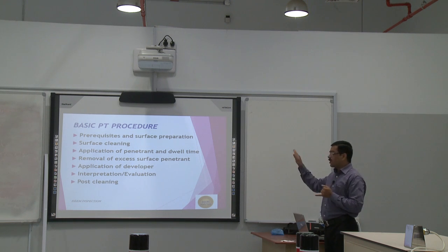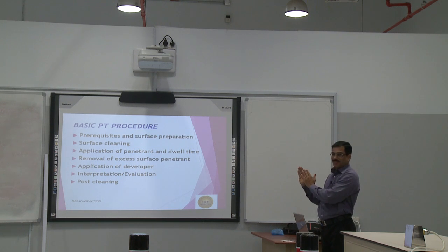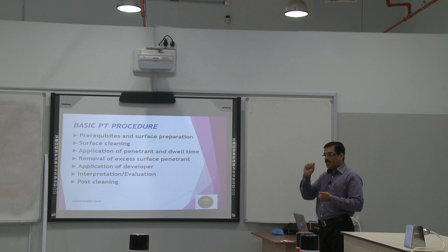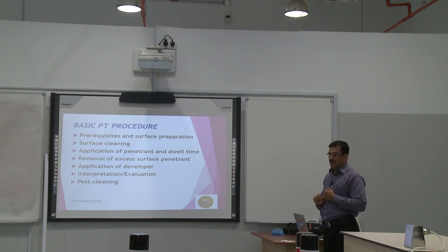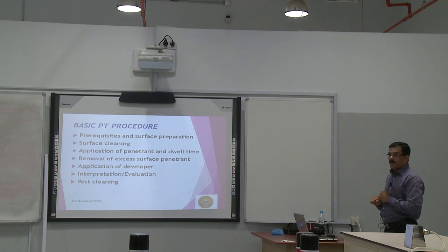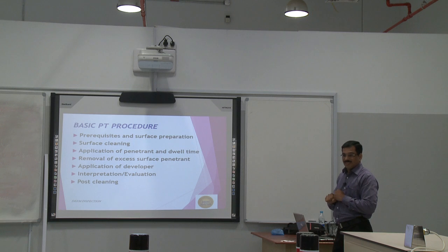Usually we make the procedure as per our experience, from our project, that this much time is required for our defects. So we can follow the procedure, or what the manufacturer says on the bottle as the dwell time. The minimum in common practice is 10 minutes.